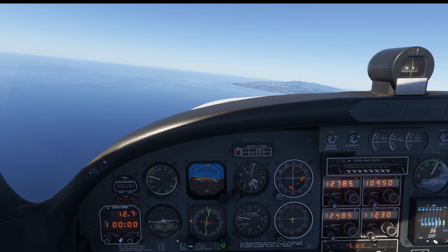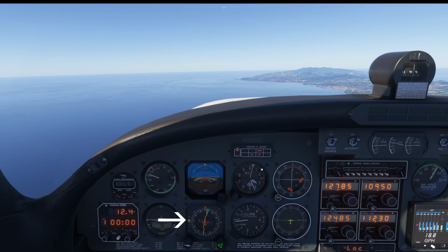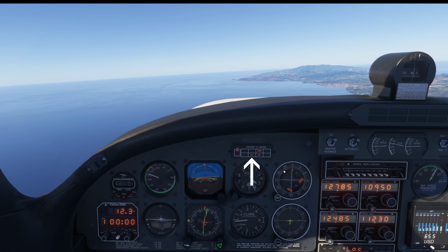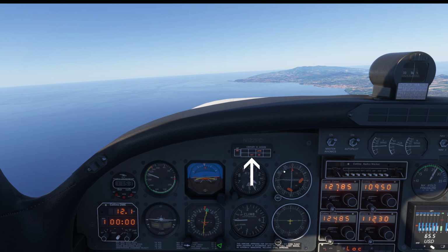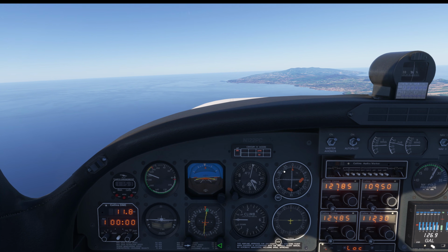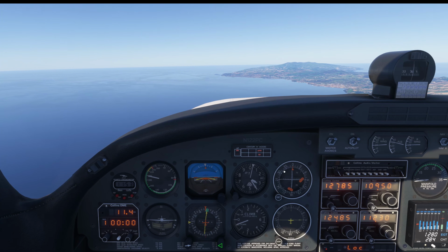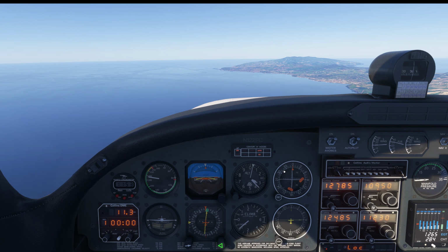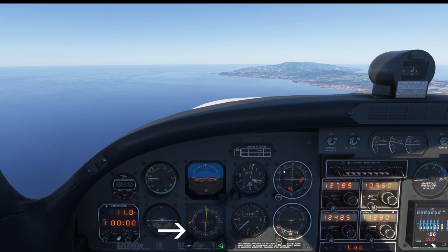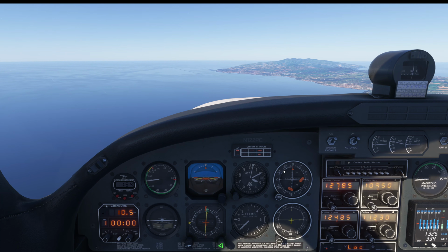In approach mode, you can also activate glide slope mode, provided that there is a glide slope signal. If you are in altitude hold mode and intercepting glide slope from below, glide slope mode will arm automatically after around 10 seconds. But it is also possible to activate it from above or from different modes than altitude hold. Simply press the button yourself. As a safety measure, if the glide slope needle falls below 80% down deflection, glide slope mode will disengage and the autopilot will switch back to altitude hold.